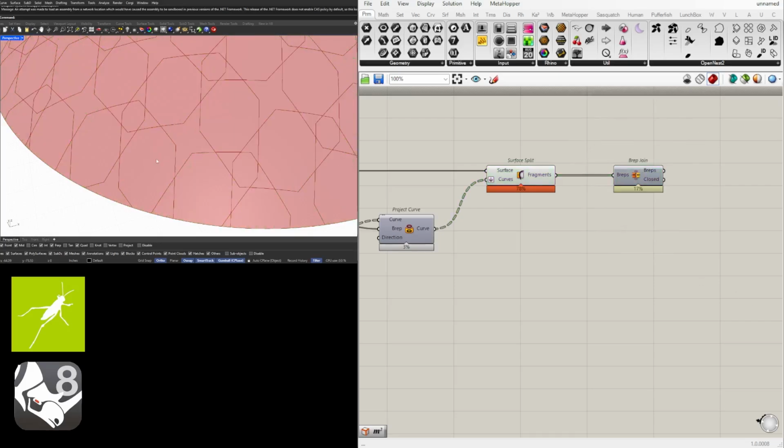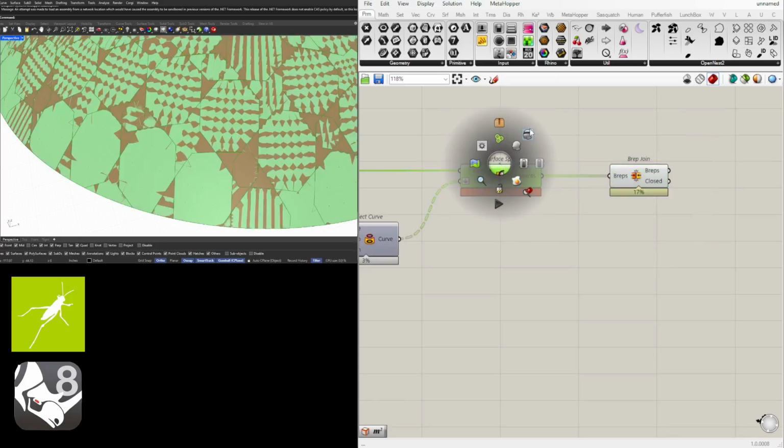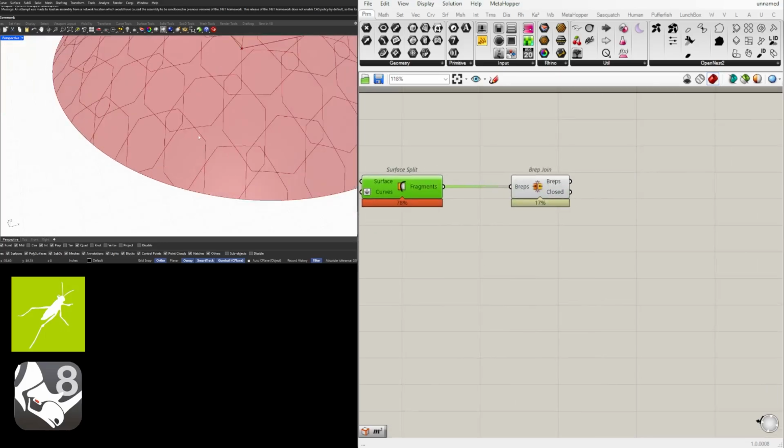If we have this surface being separate than this one, then for this surface we have a line segment, and for this surface we have a line segment, which will make us have redundant lines. But when you join it like this, now it's all joined, and these are just creases within a surface, which means that there's only one line that is corresponding to both of these.